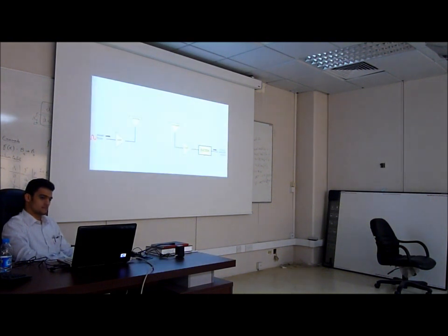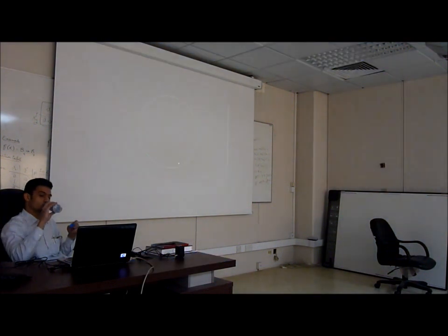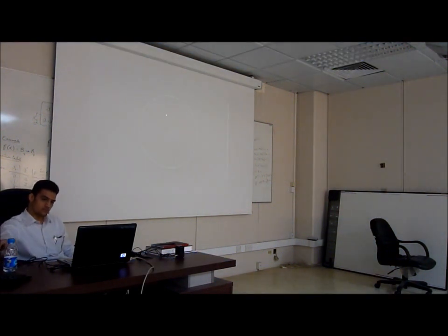the tower. All we need to do is add a filter to the radar receiver that eliminates returning pulses with an unchanged frequency. When a pulse returns with a changed frequency, it is allowed through the filter and onto the display. So now when we are tracking the jet on the radar, we only get the moving object with none of the clutter.